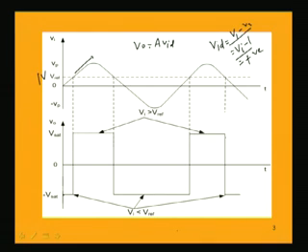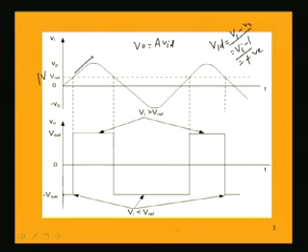So, like that we will be getting a digital pulse, that is, here we are getting a voltage between two discrete levels only, V saturation and minus V saturation. So, this is like a digital voltage we are getting, which is only in two levels, instead of the input voltage which is analog, a continuously varying voltage, and at the output we are getting a digital pulse. So, this comparator is giving at the output a pulse like this.